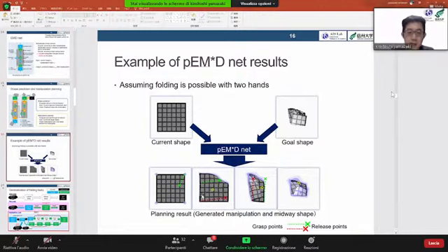We decided on about 6 millimeters per one manipulation, because we have about 200 or 300 millimeters for one manipulation trajectory, and we divided the trajectory into 50 steps. So it means about 6 millimeters. This was our finding as a good frequency.